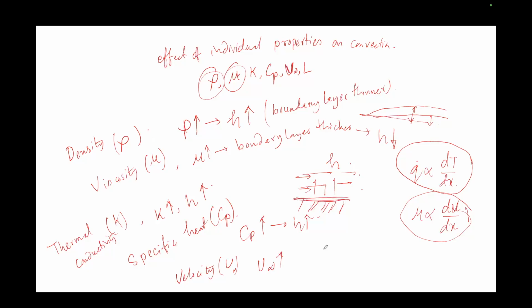Now if you are blowing air over this plate of tea, what will happen? It will cool easily. If the air that you are blowing has more velocity, then it will cool faster. So that means if the velocity of the wind, air or any source is high, it directly means that the heat transfer coefficient is more.